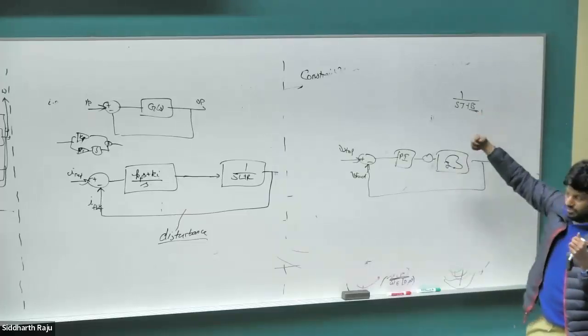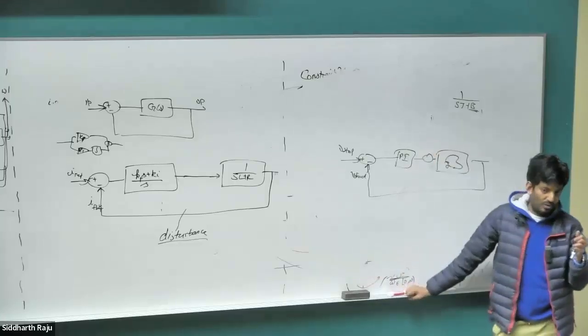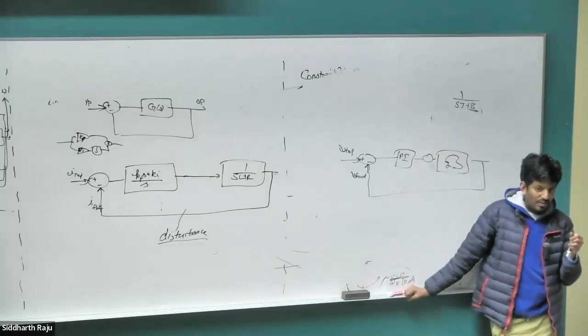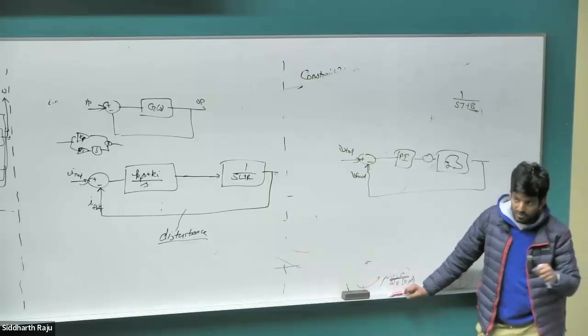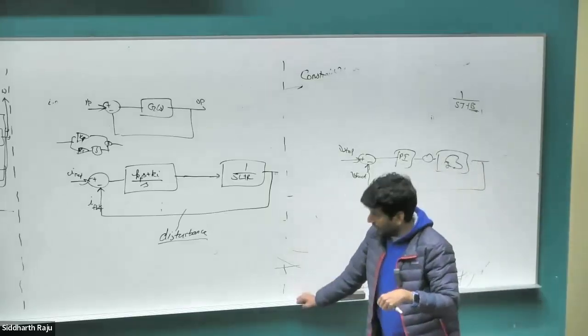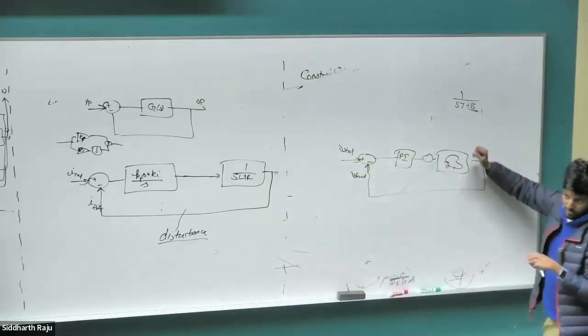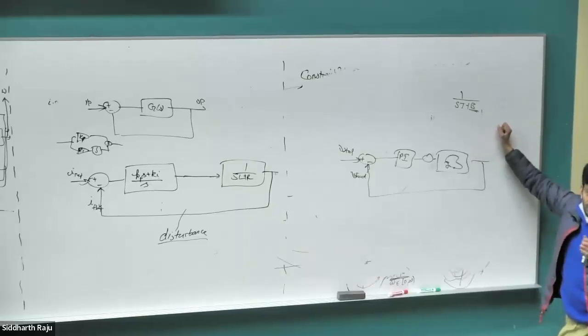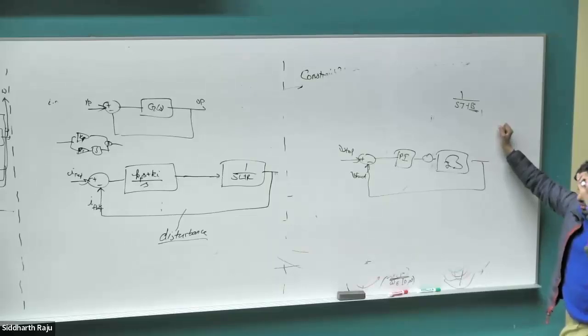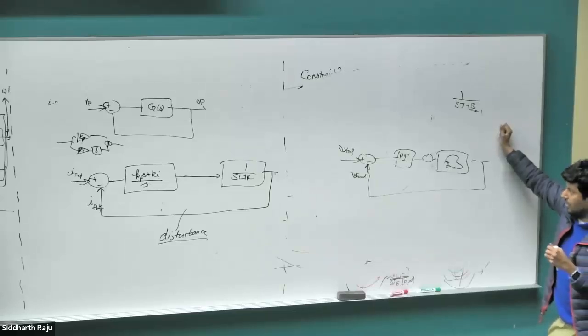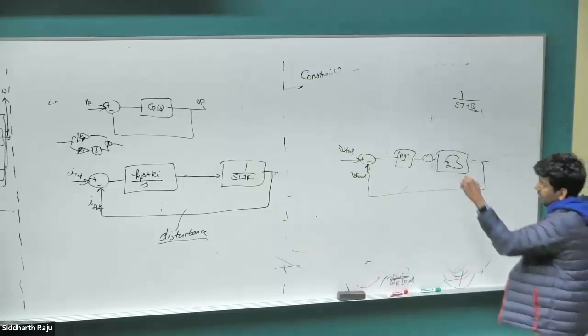Some of the disturbance needs to be something external to the system that's already been modeled. Let's say you're driving on it. Sorry. You get wind gusts though, right? Wind gust, yeah, oh, perfect. That wouldn't be modeled as part of the system. So you can have wind gust or some condition changes. You're driving on a flat road and suddenly the road starts to curve, or you start to get a slope, right? Or a mat is stuck in between the gas pedal. You need to put a little bit more gas so you can clear it. Right? All of those would be disturbance terms.